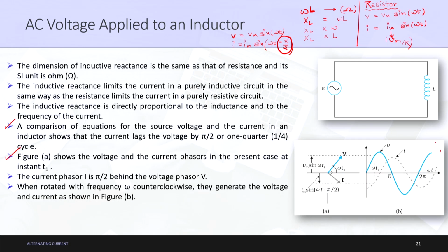Now, for a similar case scenario, if we try to find the oscillatory waveform for both, what will we do? Let us say we are trying to find the position of this phasor diagram in reality, or basically how it is in the sinusoidal waveform. We will draw a horizontal line at some time t1. This time t1 is already known, so we will just draw a vertical line again. The point at which this meets will be the value of voltage at time t1.